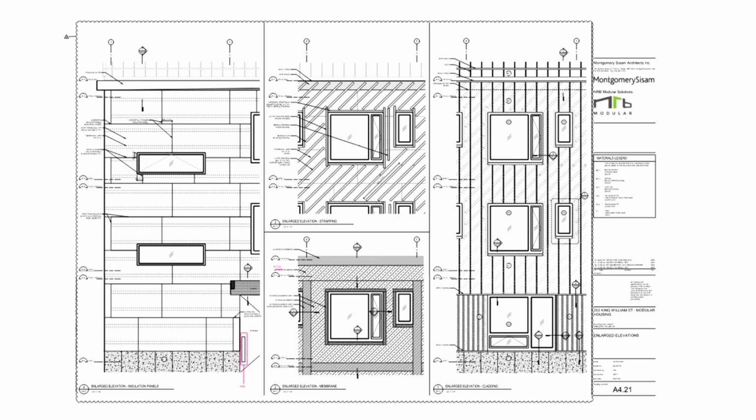Everything from the membranes in the center at the bottom, how we wanted the insulation stacked in order to reduce penetrations insofar as possible, the strapping drawings at the top, and then ultimately the standing seam cladding on the right. These are demonstration drawings just to talk about the sequence. There's obviously much greater detail in other elements of the package.